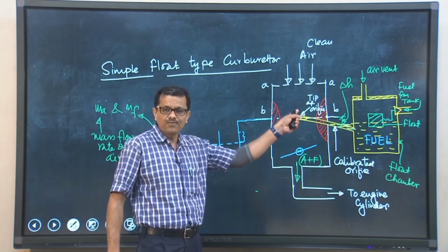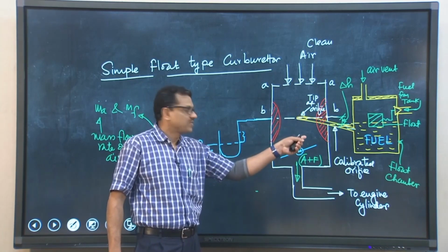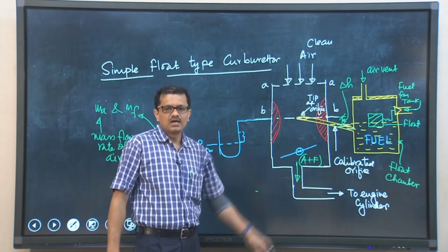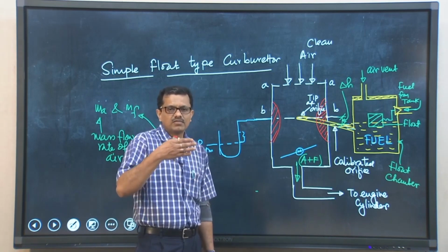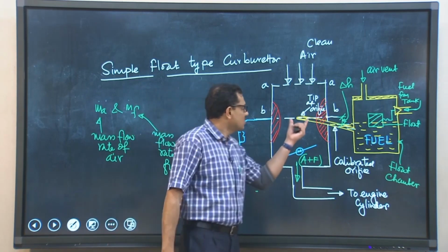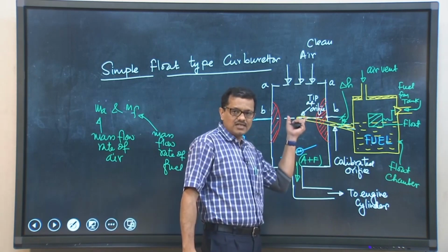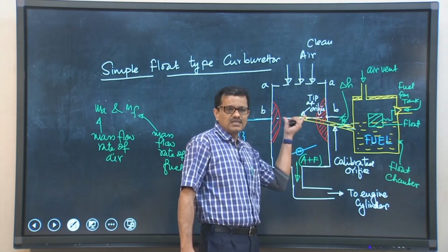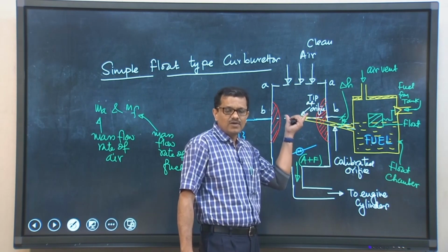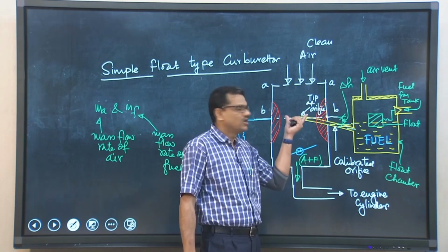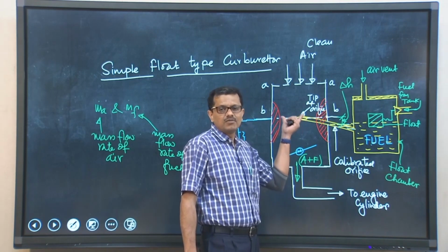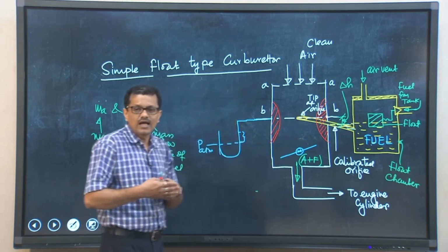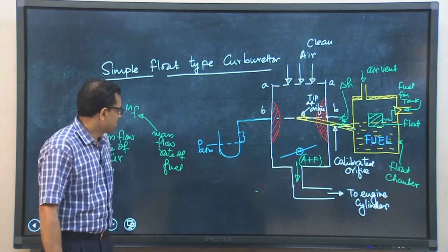That means, the mass flow rate of fuel should be adequate for the requirement, that will vary with the load of the engine, and also a reduction in cross sectional area will increase the velocity, but if the area is reducing, the mass flow rate of air also will reduce, so the designer should be careful while designing the system that the mass flow rate of air should not be compromised. So, this is what is important to have the optimum design of the Venturi.